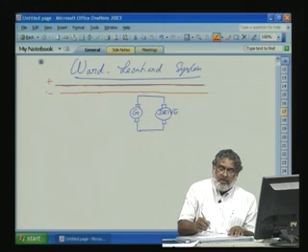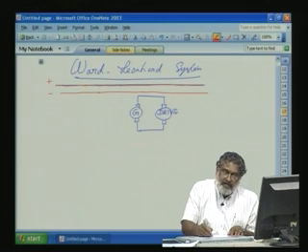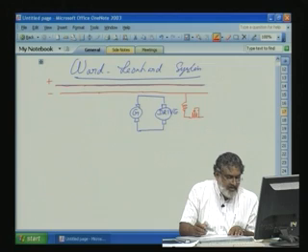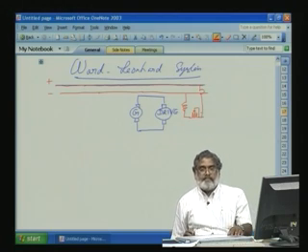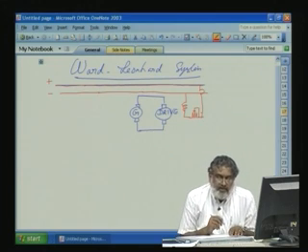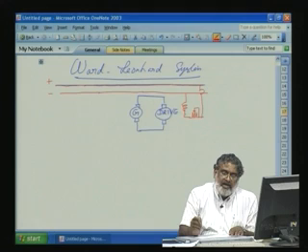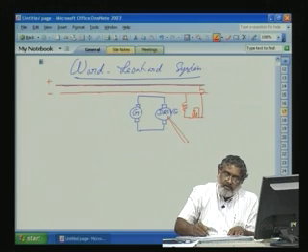So, this machine has our field winding. Field winding we are connecting here through a rheostat, we will connect it to the positive side here. So, this shows by varying this resistance we can have the field voltage also in our control. So, that also we are going to use. Now, to this machine the load is connected, load for variable speed.